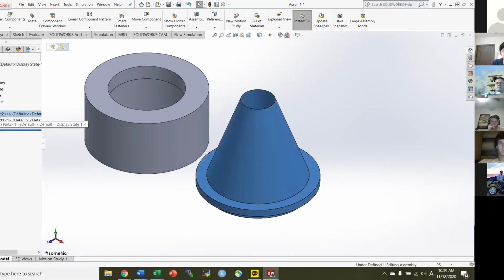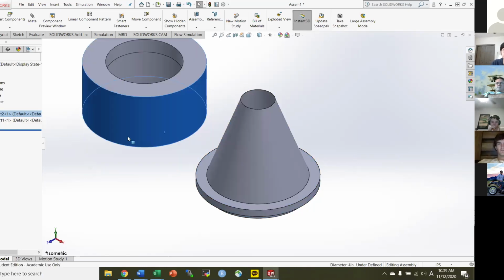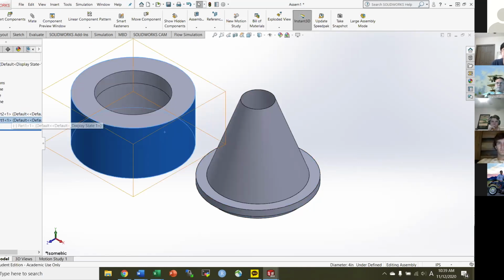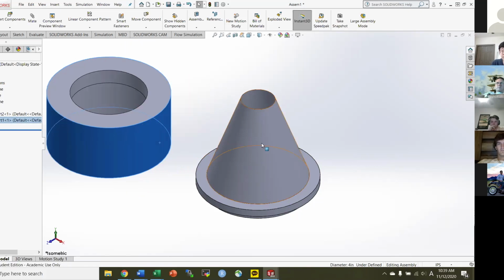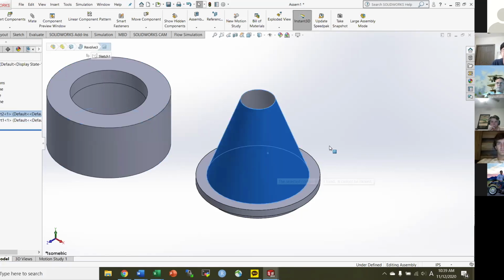What this means is the F means it's fixed on this plane. So if I try to move this part around, because this has a hyphen, it can move around freely, but the F means it's fixed. So if I try to move this part around, it won't. If I try to drag it all the way across the screen, it's just fixed, and it'll show me a message saying that the selected component is fixed, it cannot be moved.